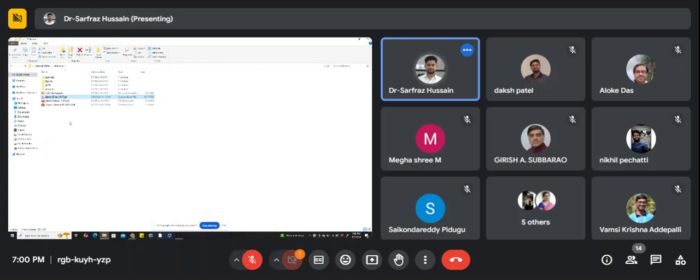permission denied or something. You'll get those kinds of errors if you don't keep this electric binary file in a separate folder. If you keep this file in the C drive, then you might get some error. So it's better to create a separate folder, and then keep this electric binary file in that separate folder like I did. I created one folder called Fabulous. There I put this electric file, and there itself I have put this GF180 nanometer technology file.